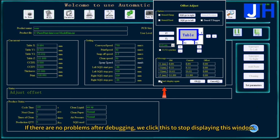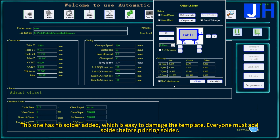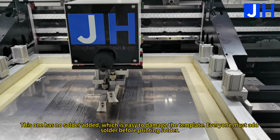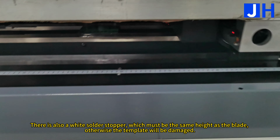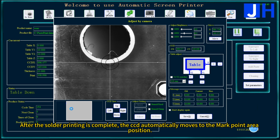If there are no problems after debugging, we click this to stop displaying this window. We click on this OK, and the machine starts running normally. For another one, we can also make the Z-axis go up or down. This one has no solder added, which is easy to damage the template. Everyone must add solder before printing solder. There is also a white solder stopper which must be the same height as the blade, otherwise the template will be damaged. After the solder printing is completed, the CCD automatically moves to the mark point area position.